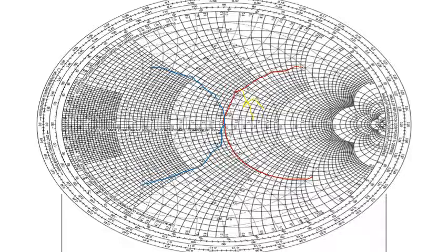Suppose you're going down now. Now this is 1.4. I'm going down along the circle. I'm drawing in green color. Can you all see this? I'm going down, downward movement. And again, this time I'm going along a dotted line. So what will happen, since I'm going down, I'll be plotting a capacitor, but this is along the dotted circle. It will be a shunt capacitor. Shunt capacitor. Are we clear with this? Fine. So we are going up and down. Anytime we go up, it has to be an inductor. Anytime we go down, it has to be a capacitor.